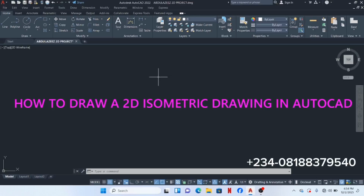So to have our isometric drawing now, we are going to have to change this interface using the Isodraft command. The Isodraft command is used to enable the isometric drafting settings. That is, from the Isodraft, I can turn on the isometric snap, or I can turn it off.